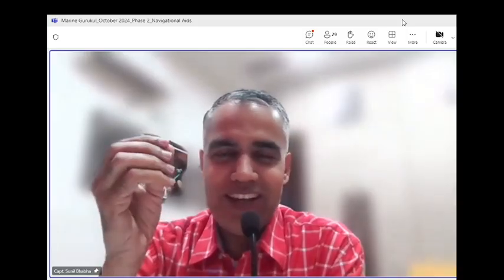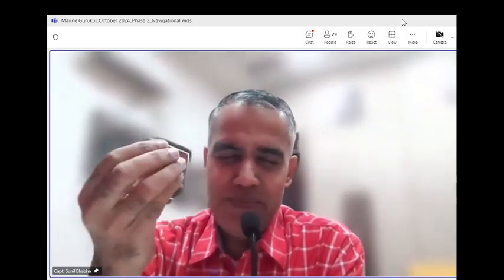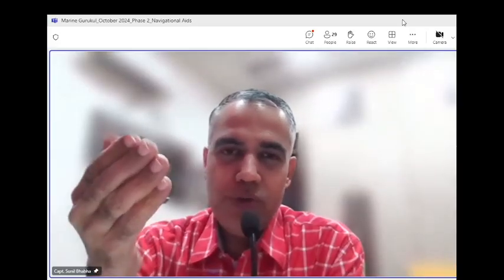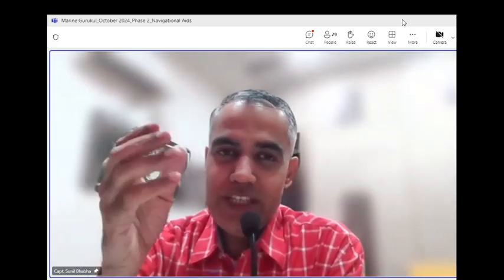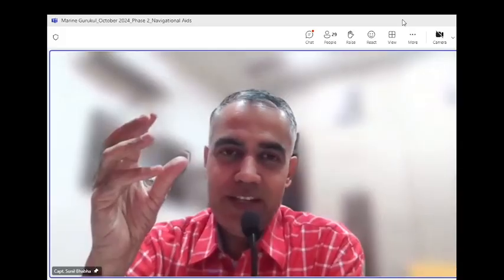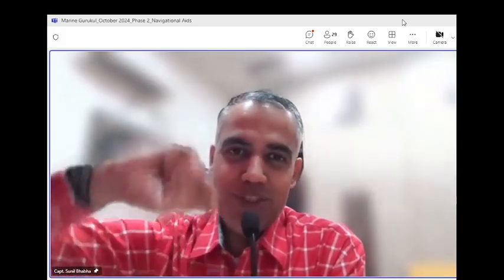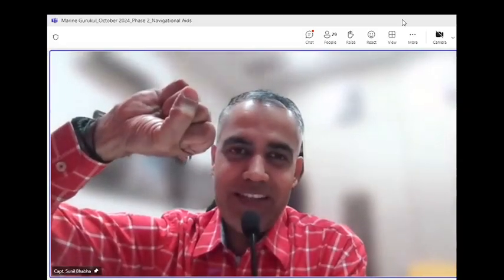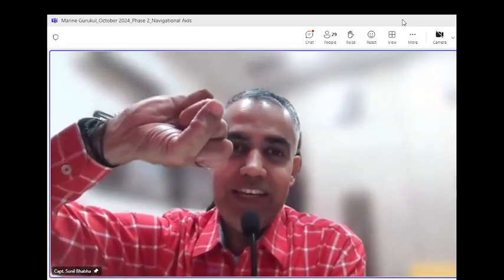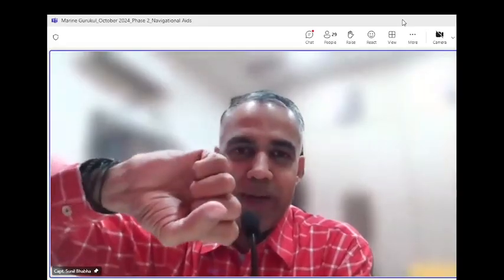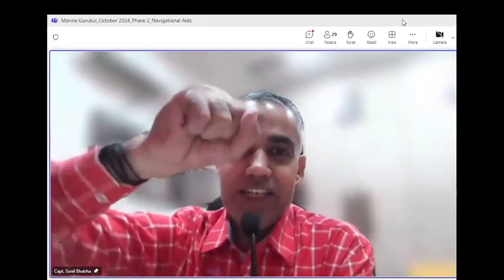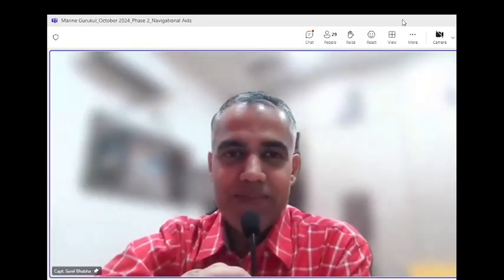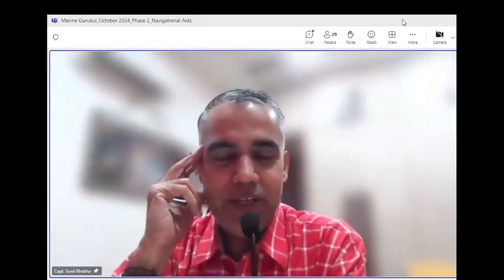I am not sure if you have sailed with old masters; fresh young masters usually don't touch the binnacle and the correctors. But if anyone has noticed, when you do equator crossing, some master may go to the binnacle. He takes out some magnets from the binnacle, from the heeling error bucket basically, and turns them. These are permanent magnets, so they have blue and red ends. He turns them and then puts them back again. Has anybody seen that kind of thing happening?